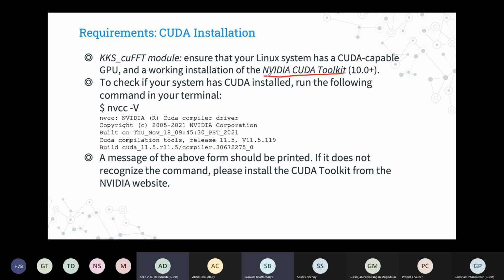The only thing is, remember, in NSM you can run much larger systems, because you have state-of-the-art GPU cards which are meant for GPU computation. GeForce cards will have lots of other usages, so you may not have so many CUDA cores, and your solutions may be very slow. However, you can run it if you have an NVIDIA card. Okay, so this is a very important thing. It has to be a CUDA capable NVIDIA card. Remember, this is something that you have to check when you buy your desktop or something.